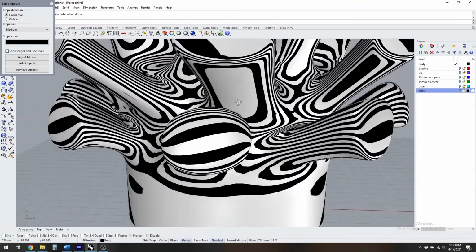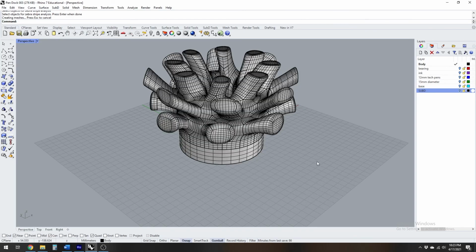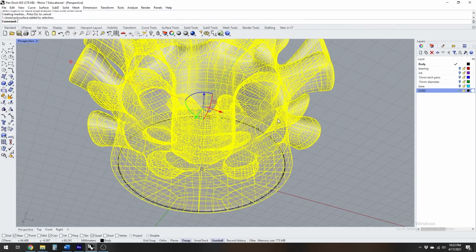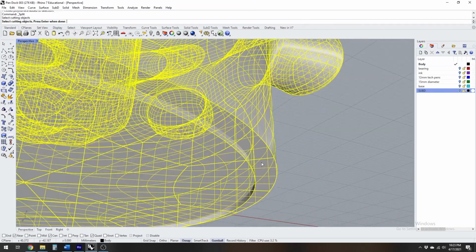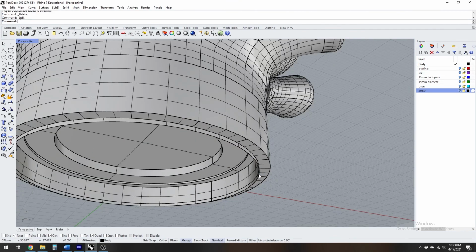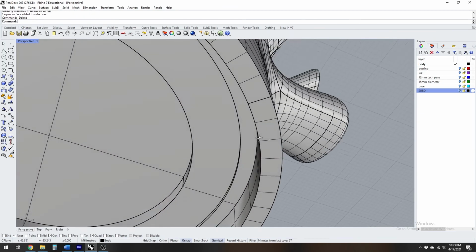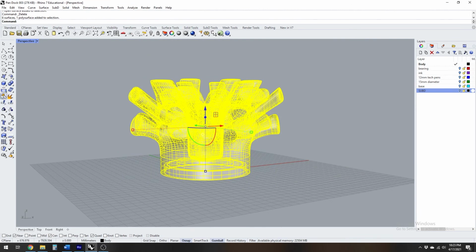With this, you're going to be able to now actionably do some traditional NURBS modeling. We can now use those cylinders for our pen diameters, and we can use the base that we already created for our split commands. Honestly, the surface responds exactly like any other NURBS surface that I've ever worked with. It trims. When we are cutting holes, I haven't had any major issues with filleting.